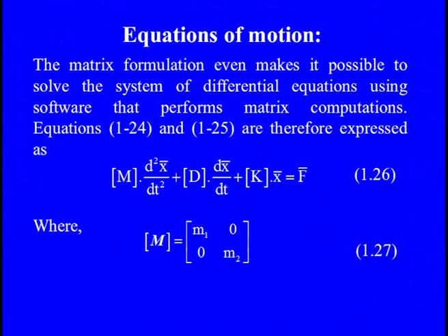We know that when you have more than two degrees of freedom, there are matrix formulations for making the equations of motion, and these matrices reflect what kind of arrangements there are, and according to the system arrangement the elements come into the matrix formulations. The matrix formulation even makes it possible to solve the system differential equations using any solving technique or software. We first need to go to the basic equations like the inertia force, the damping force, and the restoring forces, and when it is excited by external forces, we can simply go to Newton's law.